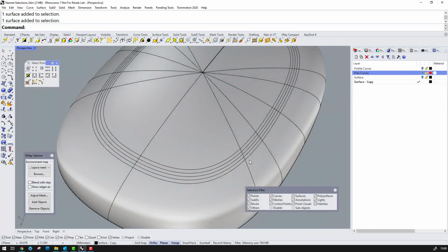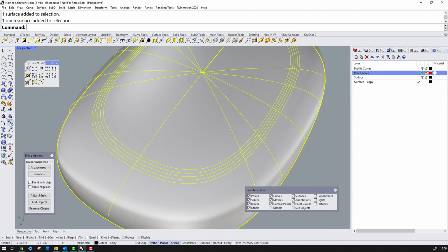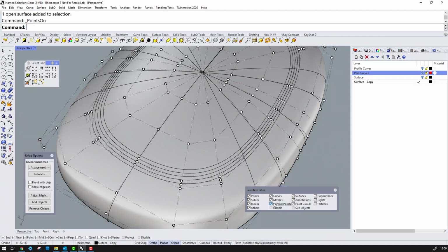To finish up with, I'd like to take a look at named selections. Now, this command is often associated with the sub-D tools, and indeed it is very useful in this context, but it's also really useful when you are control point editing, for example. As you can see, here I'm selecting part of a row of control points in order that I can move them to bring out a surface feature here. Now, of course, if I wanted to select some of the points within that range, and not all of them, then I'd have to deselect and reselect, and this could be quite tiresome.